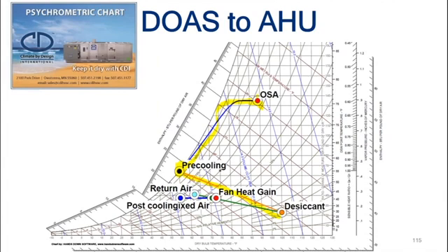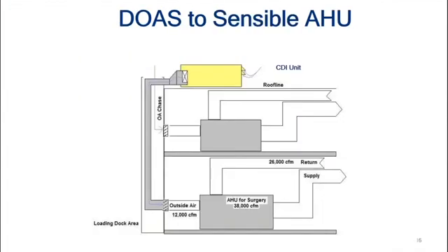We go through the desiccant dehumidification. Relatively long line again. Why? Because that's only 4 air changes. We're going to then provide that air to the outside air connection on the air handler. That's this condition. Here's our return air, relatively short line, so there's a lot of air at that condition, 16 air changes, a little bit of fan heat, and now we're going to post-cool it to the condition. So reheat's not required. Dedicated outside air to the sensible air handler.